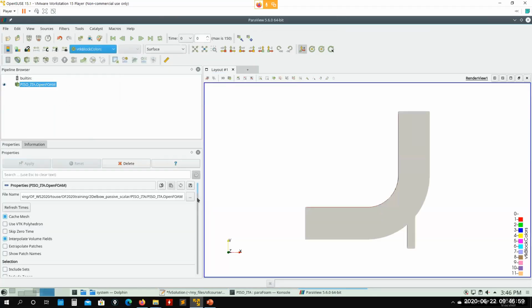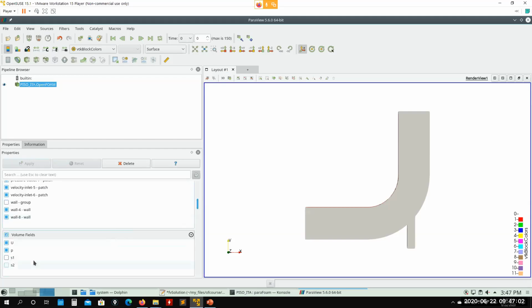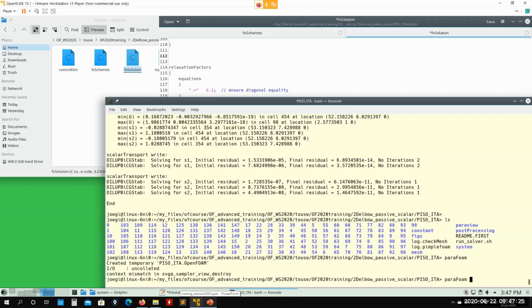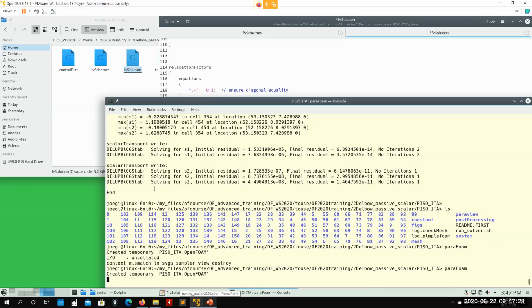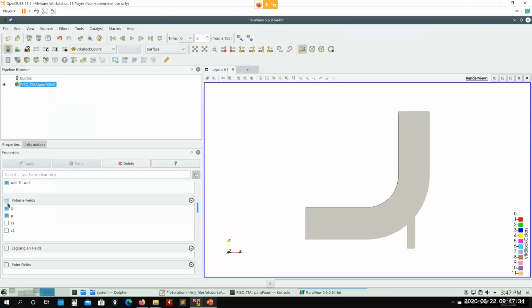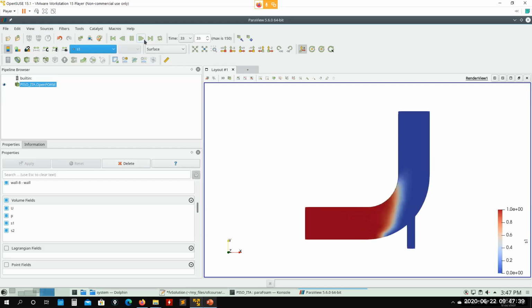By the way, what we're injecting, in the classical pipe-to-pipe case, is a passive scalar here and here, and see what happens. It is being transported. Well, actually the under relaxation didn't enter into action. I think I didn't save. Okay, we have now the solution. Remember the solution was with under relaxation 0.5. In theory, we have time accuracy here. This is time accurate. Even if it's 0.5, I recommend you to use 0.7.